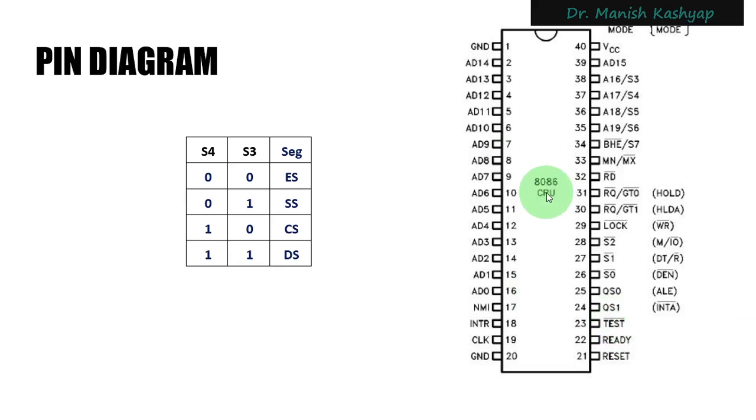There is a WAIT instruction in the 8086 microprocessor's instruction set, and this TEST signal is used with that instruction. It is usually connected to the BUSY pin of the 8087, the math coprocessor, for proper synchronization between these two devices. Because if you give a command from this device to calculate the sinusoidal value of something, it will return the value after calculating.